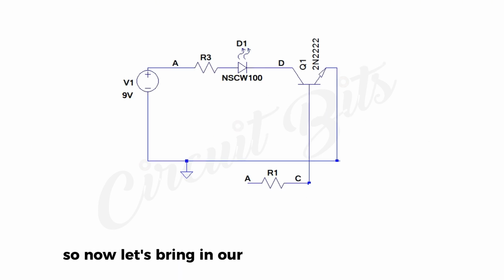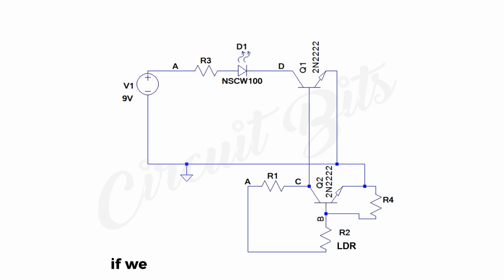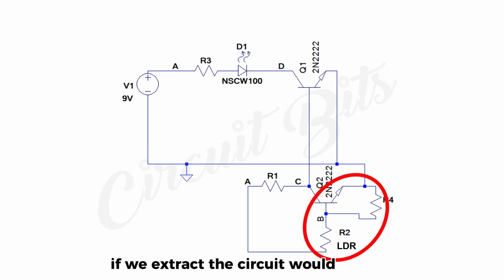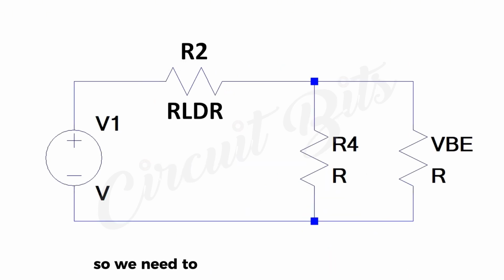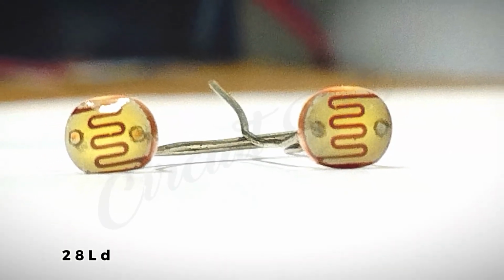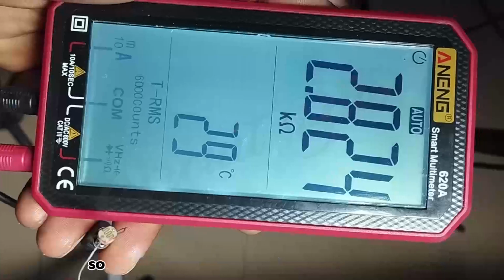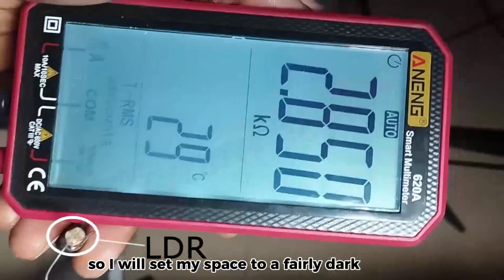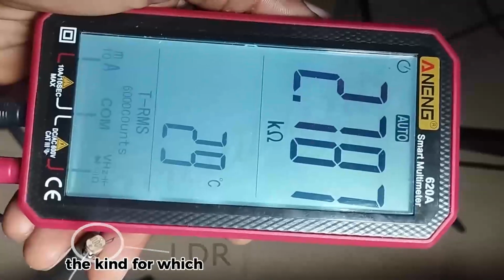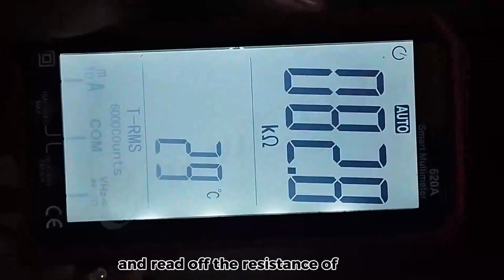So now let's bring in our transistor controlled by the LDR. If we extract the circuit, we would have this. So we need to find R4, but first we have a 5528 LDR, and when it's totally dark, its resistance is 1 mega ohm. So I'll set my space to a fairly dark situation, the kind for which I will want my resistor to turn on, and read off the resistance of the LDR, and I get 500 kilo ohms.